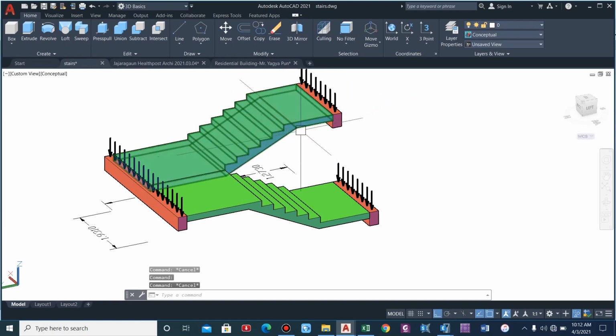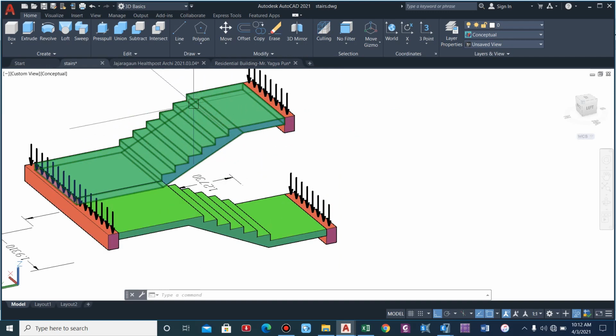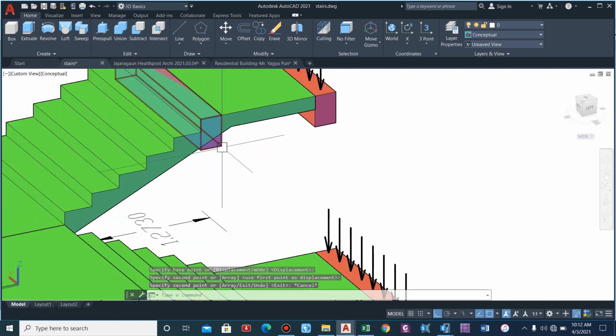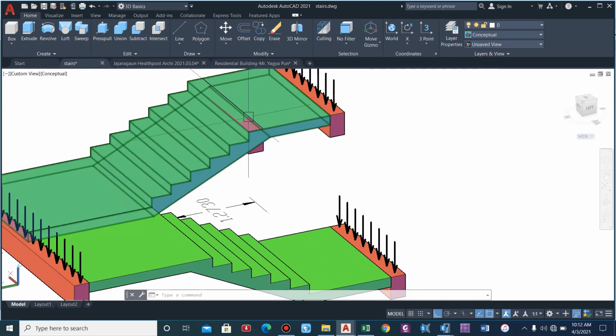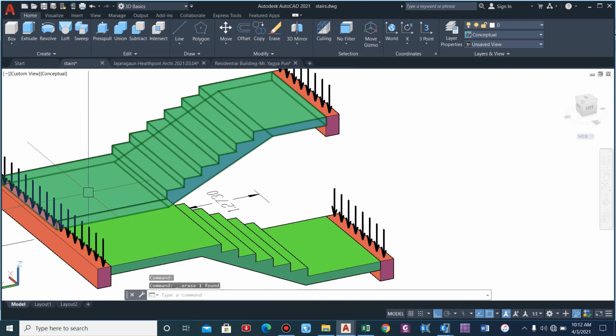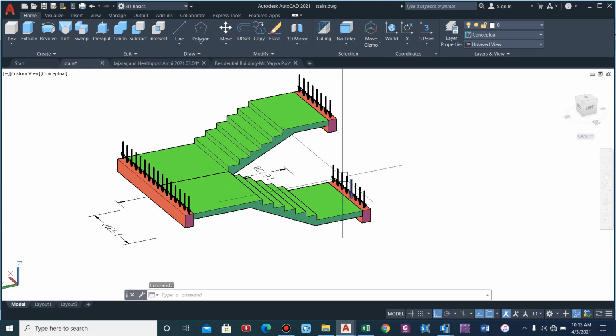So in this way we have to calculate the staircase load. In some cases you will see that the landing beam or the floor beam is provided just beneath where the landing starts, suppose over here. In that case we will not compute that load considering it as a staircase block, we will just compute considering the flight and the mid landing. And in case there is no landing beam provided, in some cases we will not provide a landing beam, then we will just provide that load to the beam just beneath the landing slab. I will show you that while assigning the load in the ETABS model.